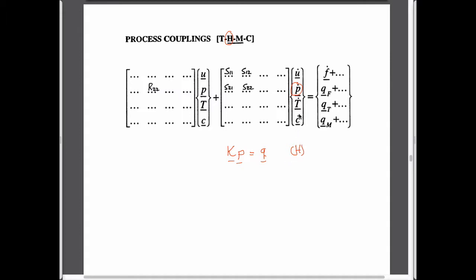We talked about advection diffusion, and we ended up with relationships that, as you may recall, if we combined an advective and a diffusive matrix, conductance matrix, operating on concentration, we ended up balancing that with a mass flux, and that is this particular one here.